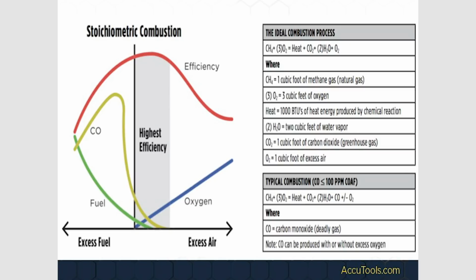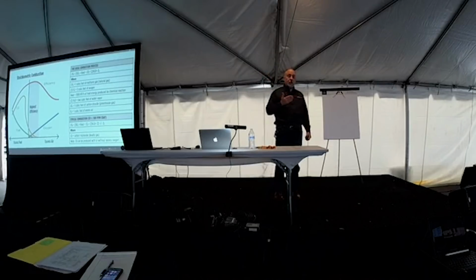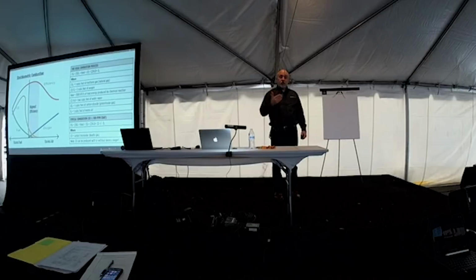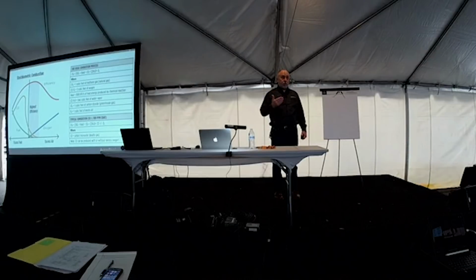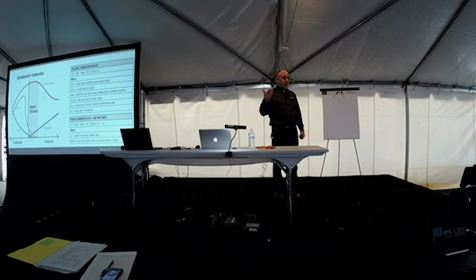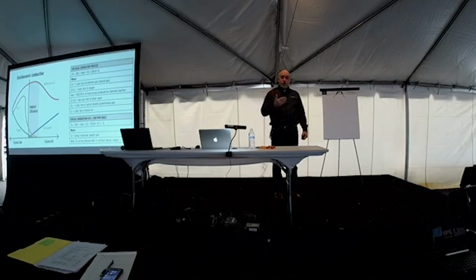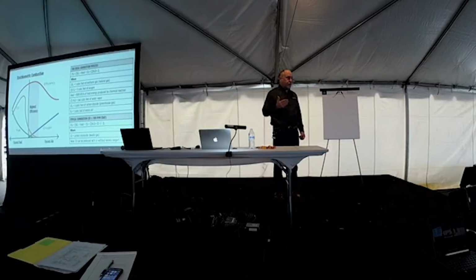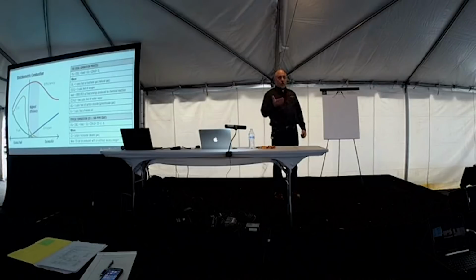Two-stage appliances do not save you any money at all. Right? They don't save you any money. In fact, your appliance runs worse on the low stage. It'll run around the 90% efficient range versus 97%, let's say, on the high fire. The only reason we have modulation and two-stage appliances is for comfort. That's it. It provides us comfort. So you're getting more comfort, you're sacrificing efficiency, okay?